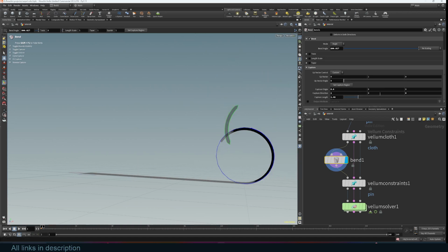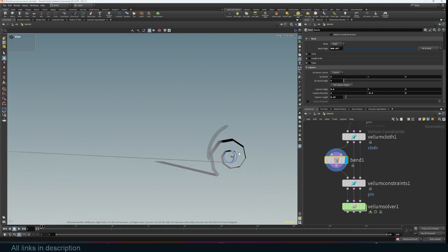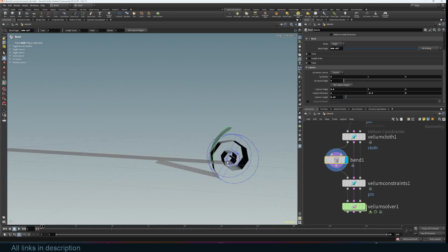So I'm also going to add some direction in the roll here. You want it to turn around like this. Let's increase the number of rolls. You don't want it to intersect because we're going to create a cloth simulation, and intersections like this can cause issues.